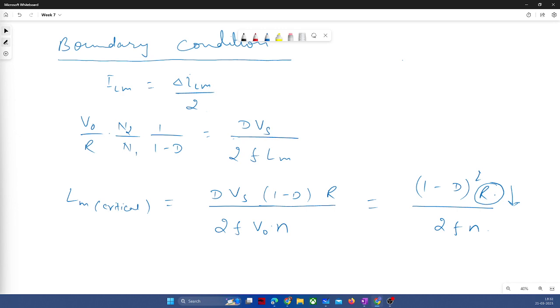If you introduce leakage inductance, your overall inductance will add up and it will increase. But just for the simplicity, we are ignoring it. That is a negative impact in terms of drops, but in terms of your inductance, it will increase. So you will require a lower size of magnetizing inductance if you have a certain requirement of overall inductance. Does that answer your question?